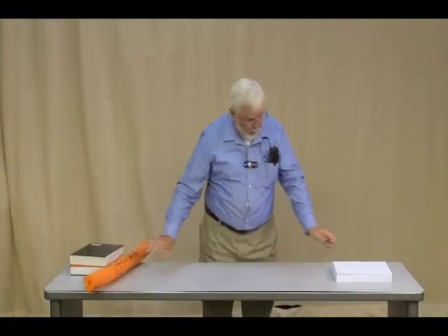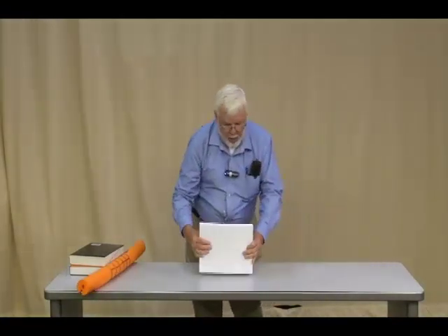Now, go back to my pad of paper for a second. If I take my pad of paper and I allow it to bend, you can picture that any of the sheets in the middle of the stack are rubbing on their neighbors top and bottom. But what is the top sheet rubbing on the top? There's nothing here to rub against, it's just air. And likewise, the sheet on the bottom has nothing but air on its outside. It does have a sheet on the inside, of course, in both cases. That means that I don't have any shear stress on the outside of the stack. So the shear stress is zero at the top and bottom, and it is maximum in the middle, where I have the most sheets rubbing on one another.